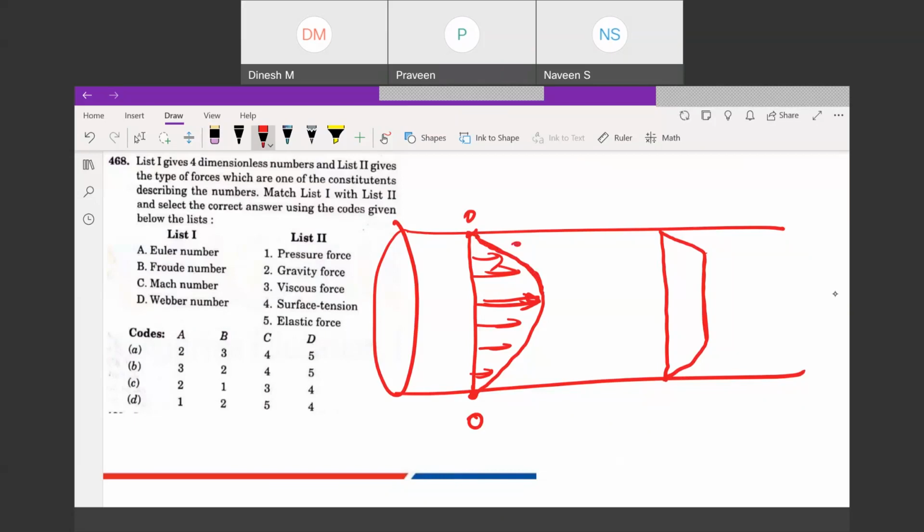In laminar flow, the molecule is not trying to shift to the nearby layer. But in this case, if this molecule is there, it will shift here, so it will increase this velocity. Then it will shift here and increase this velocity. At this location, its velocity could have been lesser, but because of movement of velocity in this direction, the velocity has increased. So the velocity profile is more uniform in case of turbulent flow compared to laminar flow. This is also one important point you can note.